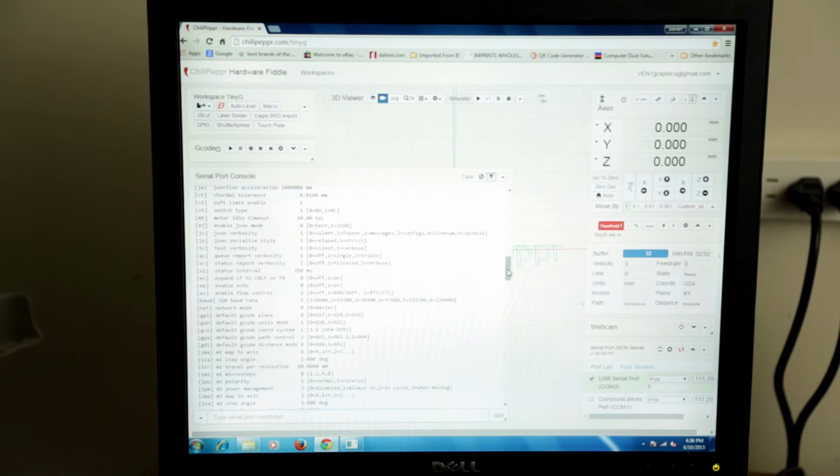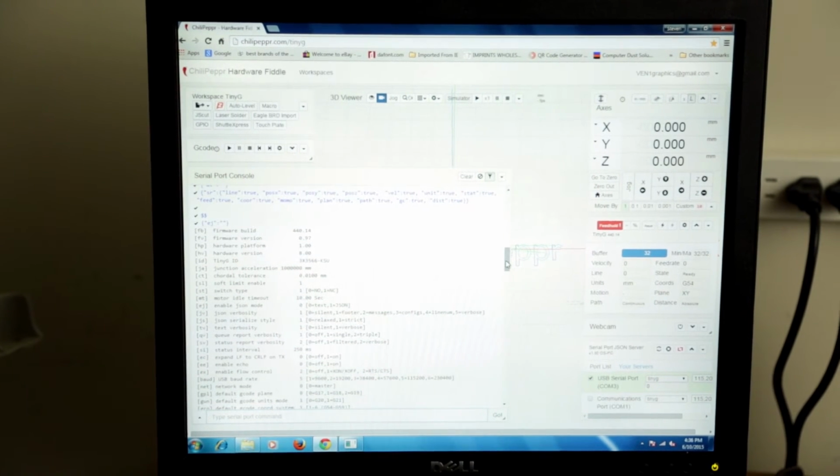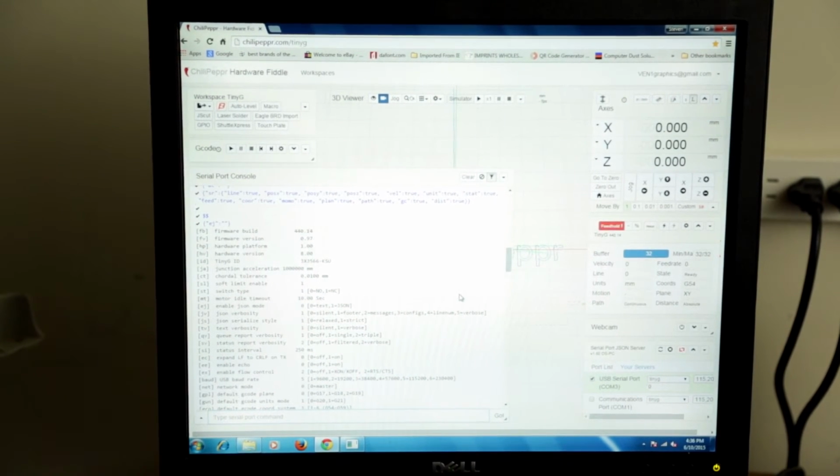So we want to go through this line for line with my particular machine with dual Y-axis. It's 1,000 millimeters on the Y and 750 on the X. All right, so that's good to know. Also important to know is what pulleys and belts you're using. We're using GT3 belts with the 20-tooth GT3 pulleys, and we're also using an 8 millimeter by 2 millimeter pitch threaded rod lead screw for the Z-axis.